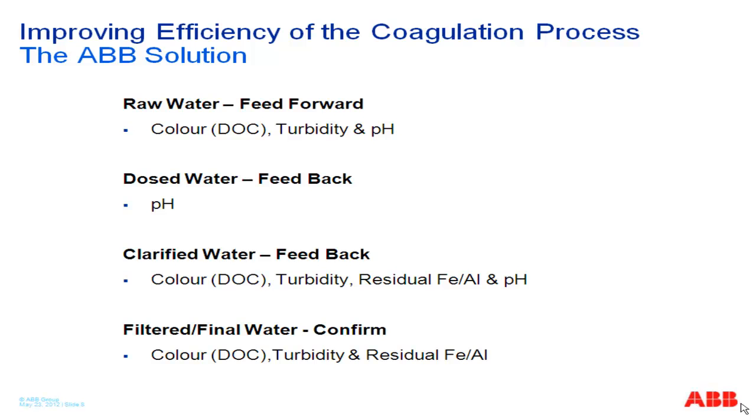We show dose water pH in here. Where raw waters aren't sufficiently buffered, people have to add an acid or an alkali to ensure that they get the dose water pH settings right, i.e. all coagulants have an optimum pH band in which they work best. So where there's a need for acid or alkali addition, it's very important that that control is good. As a raw water is changing, if you are chasing it correctly with your coagulant, you then need to follow that with your pH correction, making sure you're keeping your pH within the right zones.